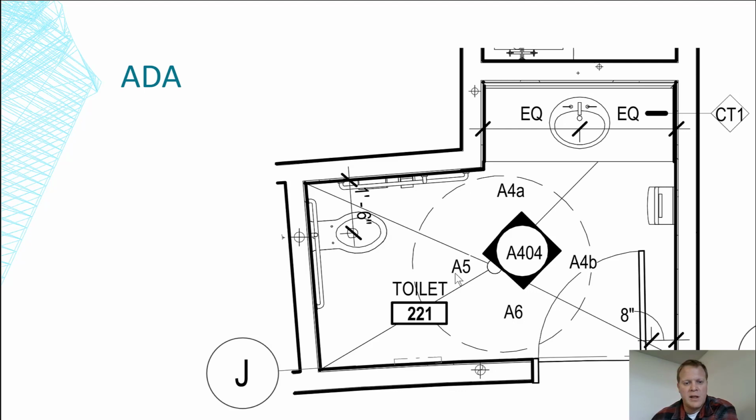Okay, cool. ADA stuff. I'm just talking about how you've got to pay attention to ADA when you're doing rough plumbing, plumbing waste, plumbing drain, plumbing piping. One thing that I don't have shown that's worthwhile is if there's no cabinet down here and somebody can pull up a wheelchair underneath, the piping has to be insulated, so that if hot water is in that pipe and somebody in a wheelchair comes up and gets their knee on that drain, it's not burning them.